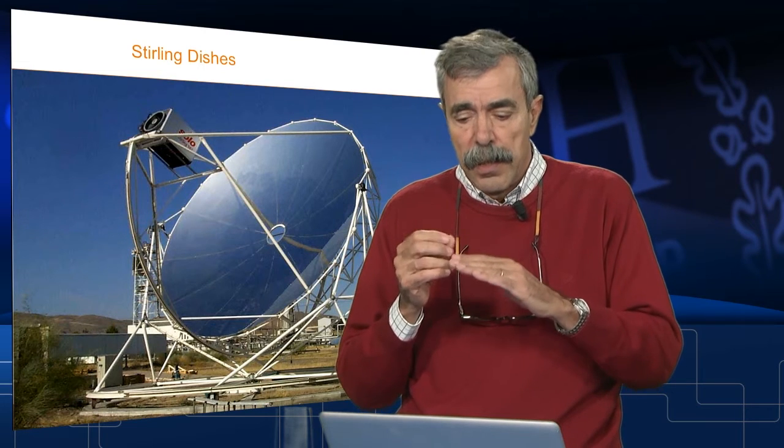But obviously, dust accumulation is going to reduce that efficiency to values that we have measured. In Spain, for instance, in the south of Spain, it means that we drop something like 6% per week. So we try to maintain the whole system very, very clean to maintain the efficiency of the system.